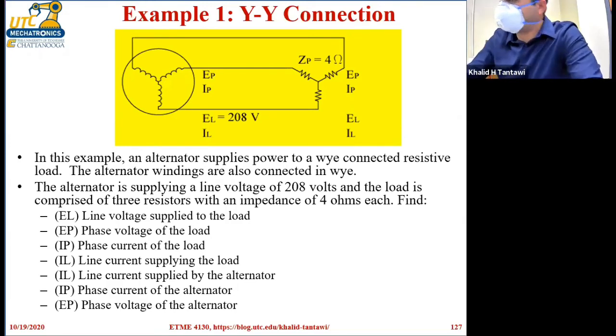It's going to be a combination, of course, of both resistive and inductive, but the inductance is going to be considerably high. It cannot be ignored. But here, just for you to understand how three-phase systems work, we're going to assume that you only encounter a pure resistive load, because if you have an inductive load, the calculations are going to be significantly different. It introduces phase shifting, and the power factor is going to be different, and a lot of things. So we're just going to encounter a pure resistive load here.